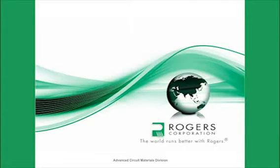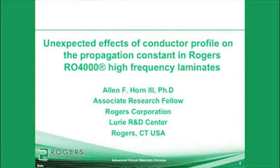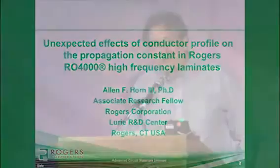It was only after I had submitted the final version of the slides that I noticed I had forgotten to mention what RO4000 materials are. Let's say, this is Rogers commercial high-frequency circuit substrate. It's based on fused silica-filled hydrocarbon resin, glass reinforced. It processes quite similar to FR4, but has excellent high-frequency properties.